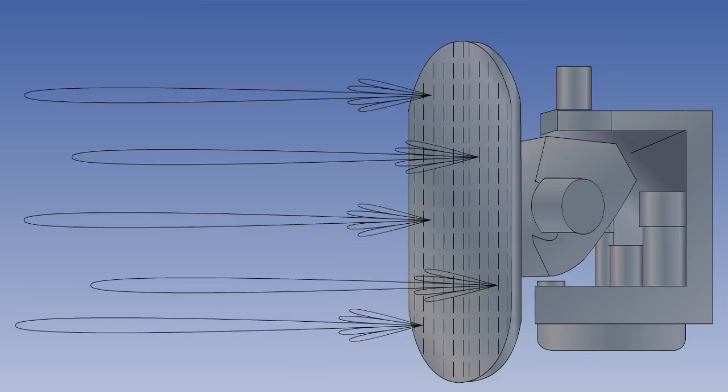This is the principle of the slotted array antenna, and the energy is emitted from the multiple slots in the plate. This type has the advantage that the side lobes are smaller, thereby wasting less power. The RF energy is therefore concentrated into a narrower beam. It therefore needs less electrical power. This makes it a popular choice for airborne weather radars.